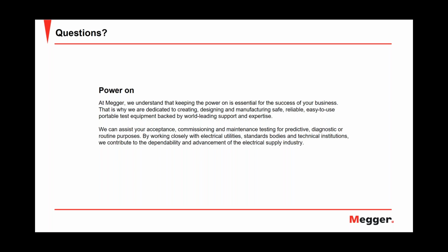Okay. So why do open conductor faults happen in the case of aluminum only and not with copper? Well, it's simple. Aluminum has a much lower melting temperature than copper has. Normally, where these failures, the open circuit, or what we call burnt in the clear failures, happen is when you have a circuit and there is a little bit more resistance at the point where the fault is in the conductor, but it's not enough to trip the fuse or the breaker. So the power continues to be sourced to that area. It heats up and heats up and heats up, and it can melt the aluminum. And in copper, like I said, because copper has a much higher melting point, normally that does not happen. Unless you have a really catastrophic failure, then you might also get a melted copper conductor, but normally it doesn't happen.